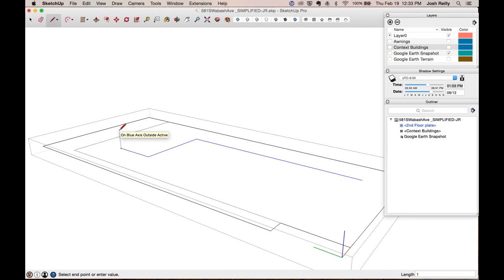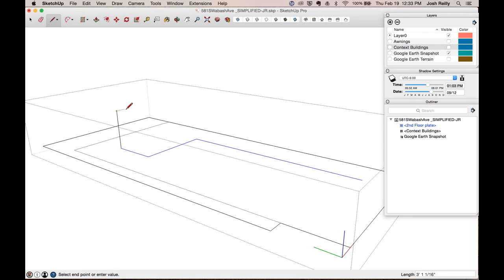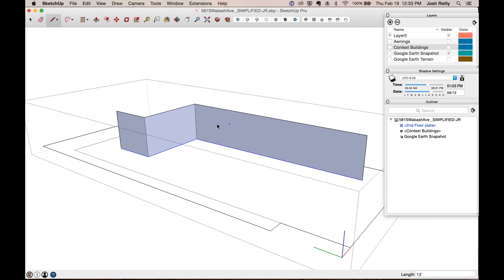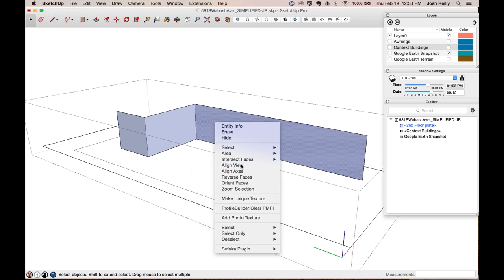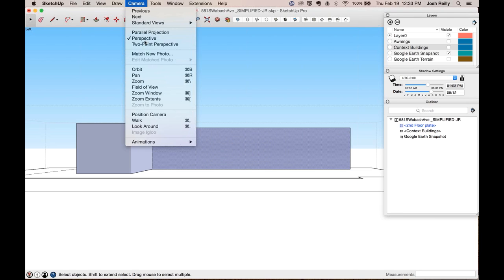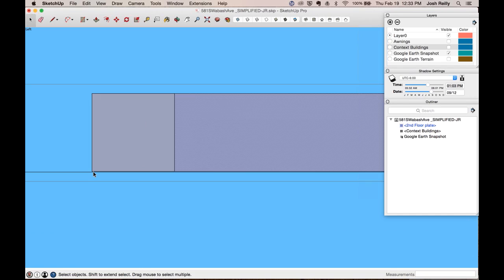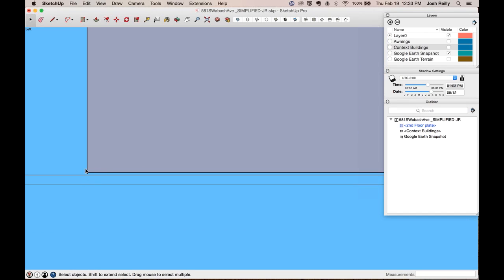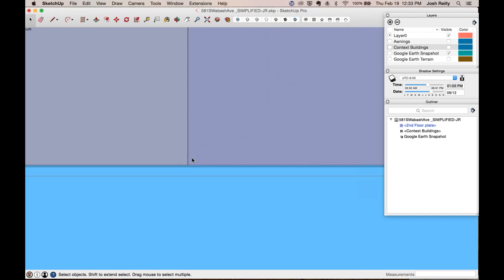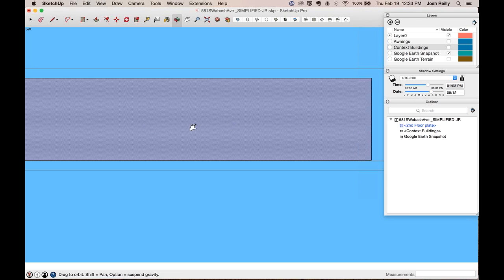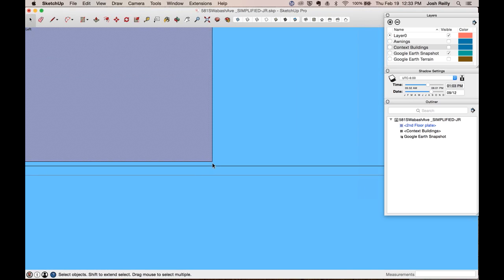Basically, if you had the bottom edges of those walls right on the floor, there would be a bit of an offset where the wall exists, and the graphic representation wouldn't be quite representative of what's really going on. So that's why you raise the base of the wall up slightly from the floor, to ensure that the graphic representation is correct.